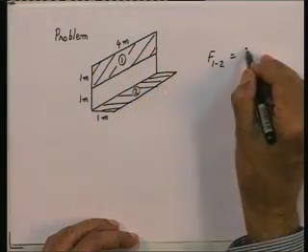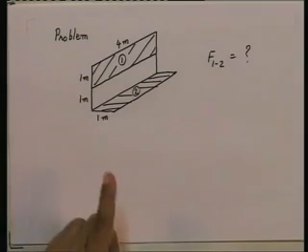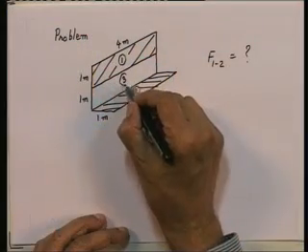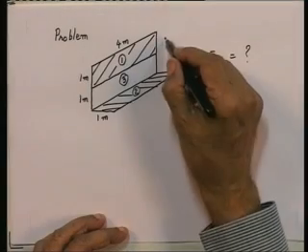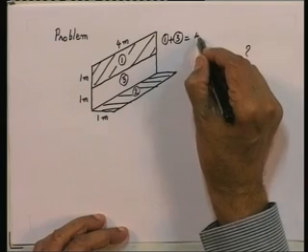We would like to get f1 to 2. Now, mind you, I cannot read this off directly from the graph which I had earlier for two rectangles with a common edge. In that situation, remember we had the common edge. Here we do not have a common edge, they are at right angles, but do not have a common edge. Suppose I call this rectangle as surface 3, and I call 1 and 3 together, 1 plus 3 together as 4.